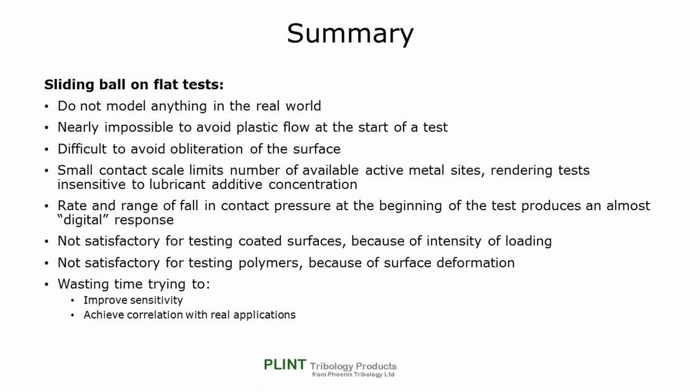And so to my conclusions. In this talk, I have attempted to explain what it is that is produced in various different sliding point contact tests. Who could have imagined how complicated it all is? For the most part, the only justification for running a sliding point contact test is that it allows rapid generation of a wear scar that can be measured, at best, with a degree of uncertainty, and frequently with not much idea of the wear mechanism or mechanisms involved.